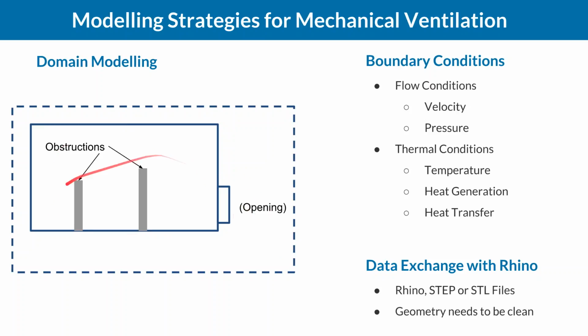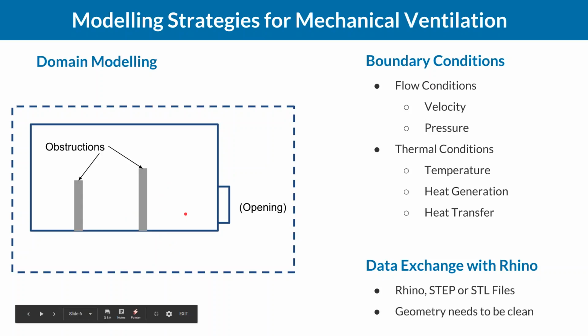And the flow is induced, and that is very important, by temperature differences. So we're really talking about natural ventilation or natural convection only, and therefore they mandatorily require a temperature boundary condition, which means we cannot simulate natural ventilation or the internal flow of a building without having any temperature differences or temperature boundary conditions.